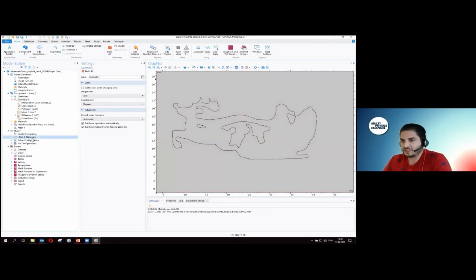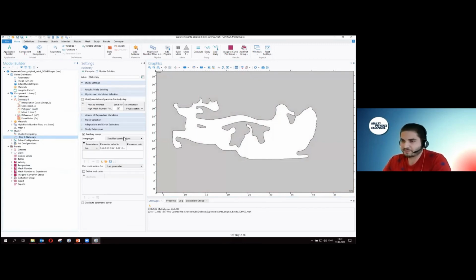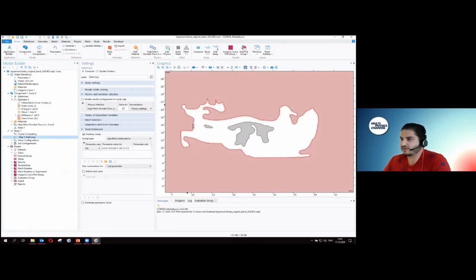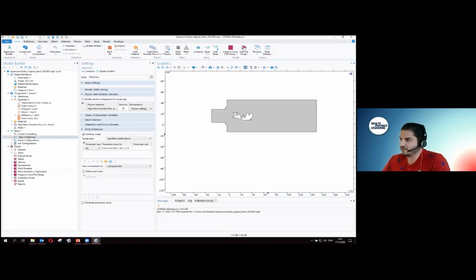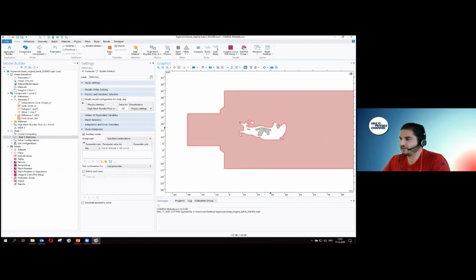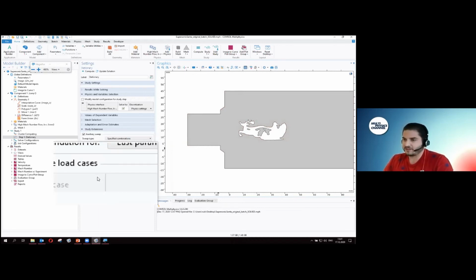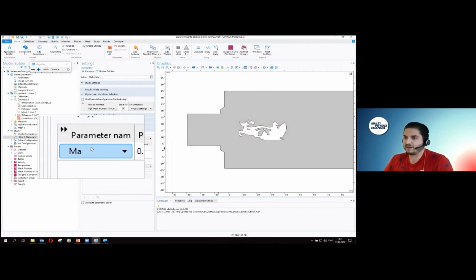When I run this calculation, of course, I won't get a solution because it is way too fast a calculation. So in this entrance here, we have the Mach number flowing in. It is about 1,000 kilometers an hour at the inlet. So that's quite massive. And here we have an outlet. And in between, in that region, a certain flow will develop. To get convergence, I'll ramp up the solution. I take it very easy at the beginning. And here you see that I chose the parameter Mach number as a ramp-up parameter.